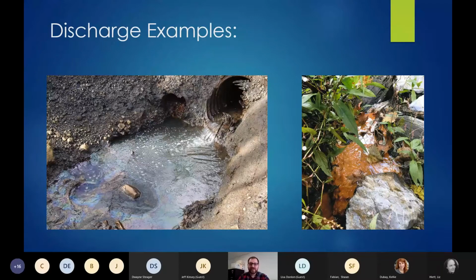It's not an illicit discharge. The answer to that is yes and no, because you have to remember what's causing those leaves to be there. If it's an oak tree that just happened to drop all of its leaves in one spot and they all decomposed, that's fine. But if a tree dropped leaves on a resident's property and that resident gathered all those leaves and just blew them into the gutter, that's not fine, because that's human interaction causing a disturbance downstream, and that becomes an illicit discharge. So it's not just what causes it, but also why was it caused that we have